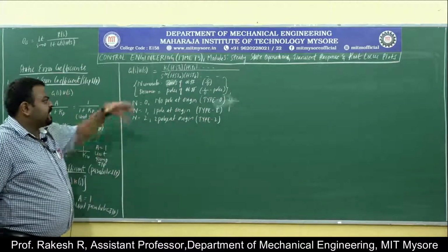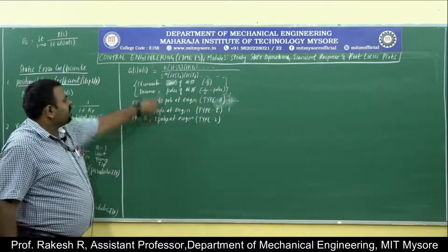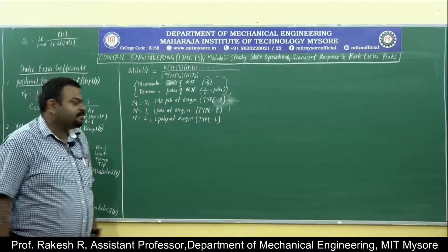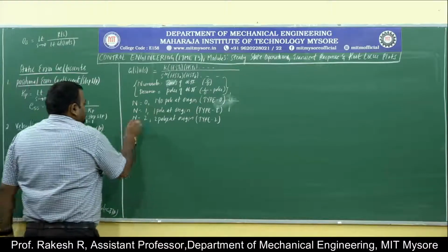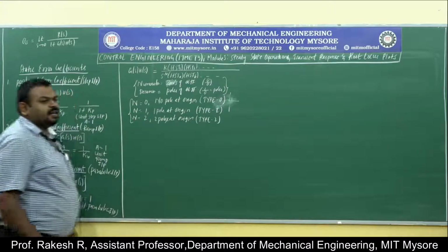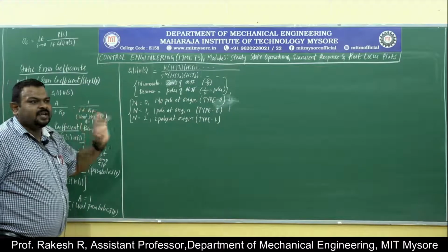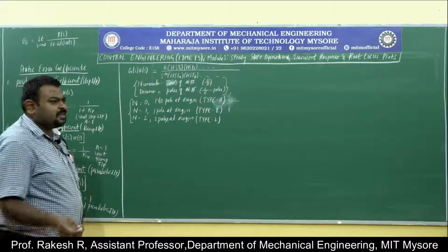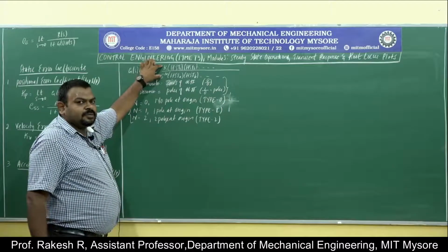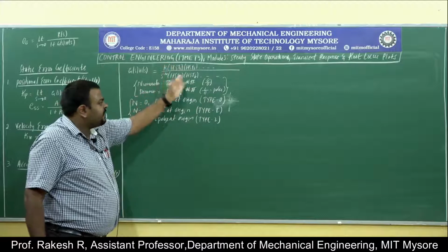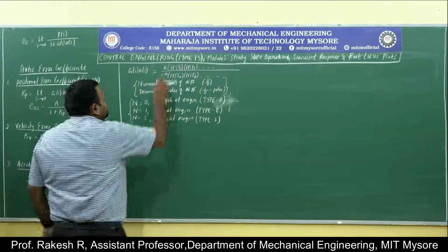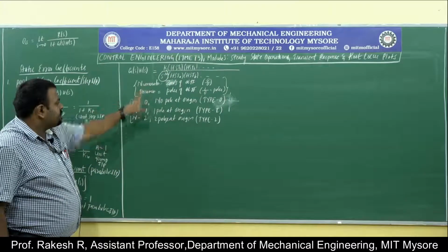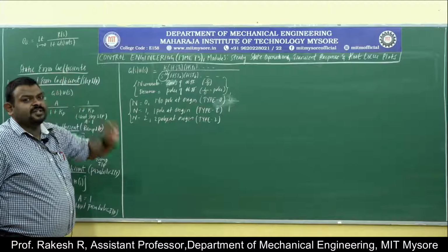Whenever we deal with the type of the systems, we will be knowing the location of poles, whether there is a pole at origin or not. So these concepts are very important in order to analyze the steady state analysis for a certain system. If I take a certain system, it consists of an open loop transfer function having terms in numerator and denominator. Mainly we will concentrate on s to the power of n, where n represents the type of the system.